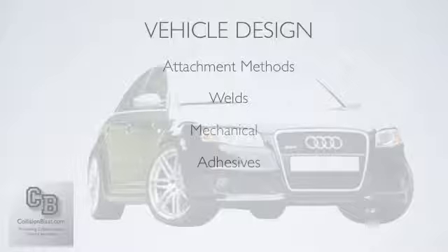There are some benefits to adhesives because they help seal out the moisture, and that's something else with these unibodies: you've got to consider rust. So if everything depends on these panels for its full integrity, rust is more than an eyesore. If you see a rust spot on unibody parts, it actually is weakening the structure of that car. So these adhesives help seal out moisture to prevent these vehicles from rusting.